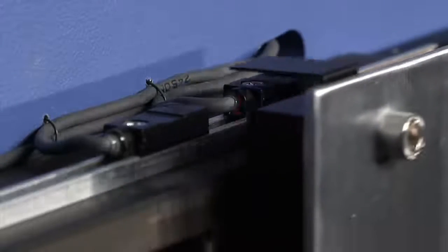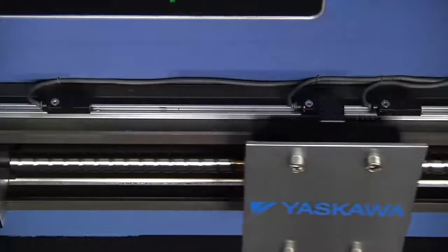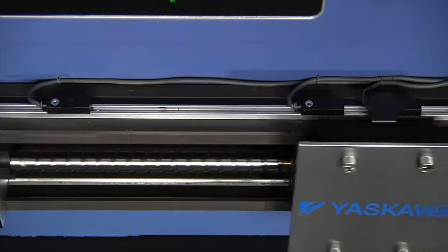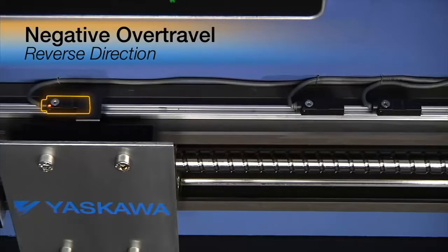the wisdom of planning for the unexpected. Overtravel inputs can prevent costly damage. Without it, moving parts of the machine could be allowed to crash into one another. Now, the positive overtravel sensor is connected to the amplifier input that stops motion in only the forward direction. The negative overtravel sensor is connected to the amplifier input that stops motion in only the reverse direction.